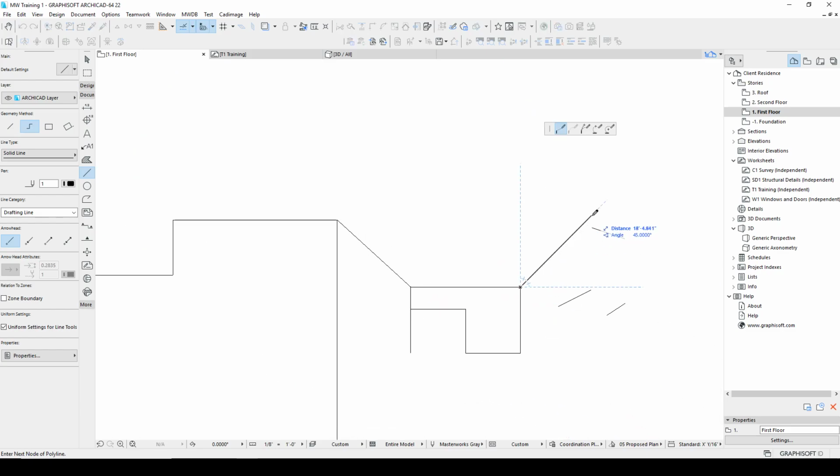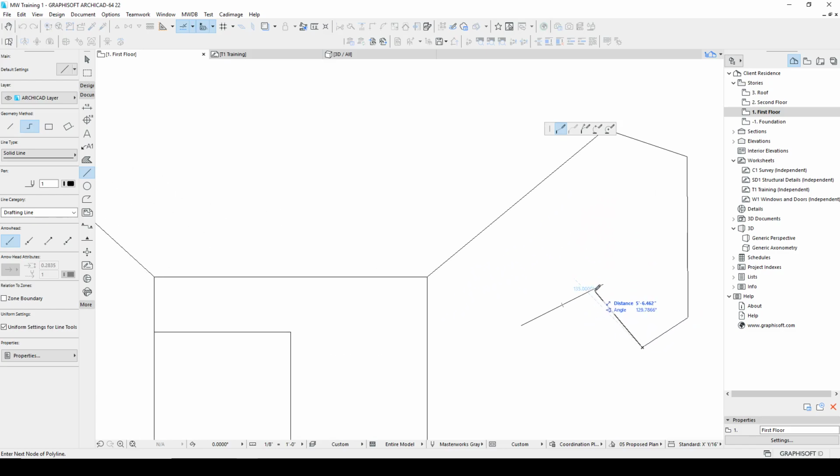So connecting endpoints is obviously pretty easy. I got the check mark on the first one, then I get a black pencil. Black pencil means that it's also found that corner, more visual feedback. Those points are connected precisely. Check mark, black pencil. I can also get a pencil with a line through it, which means that I'm not on the endpoint, or I'm not on the midpoint. You notice the midpoint's jumping up here, and we'll take a look at that in a minute. But I am connected to the corner here.